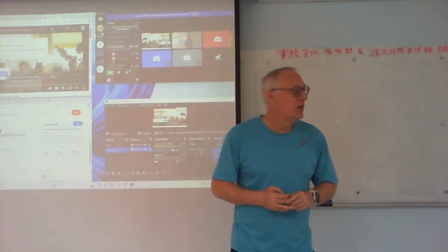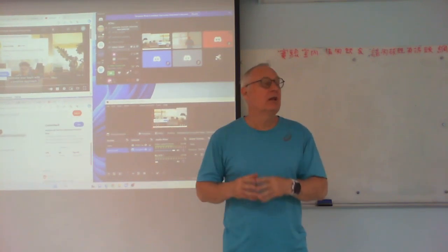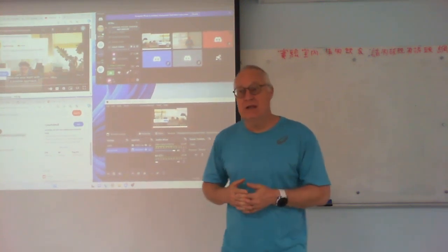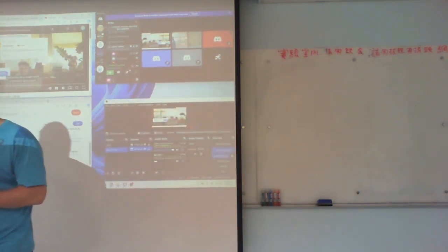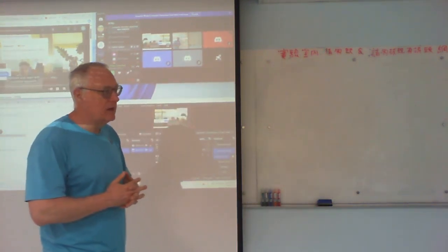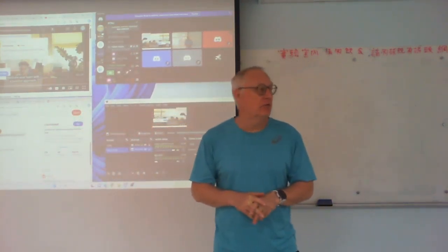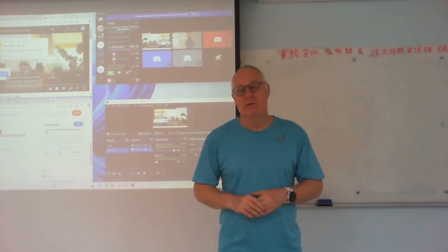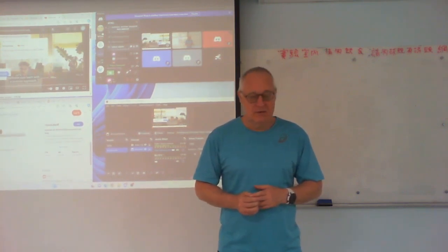Now in that case, you don't talk about a visual SLAM algorithm, but that kind of algorithm would be called a visual odometry algorithm, because we're mainly interested in the motion that we're doing, our current velocity, our current turn rate, more so than building a map of the environment. That's kind of a secondary concern. But getting real-time information about the velocity was very important. So that's what we were doing with the camera.